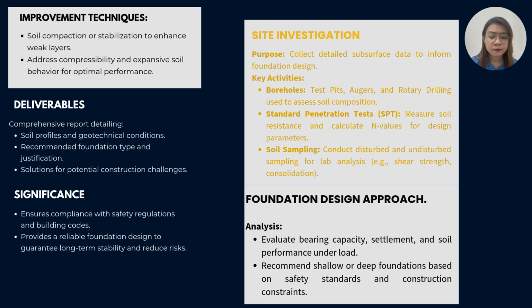Our purpose of our site investigation is to collect detailed subsurface data to inform foundation designs. So key activity, which is first borehole, test pit, auger and rotary drilling used to assess soil composition.